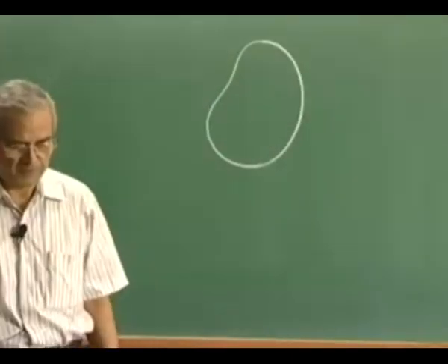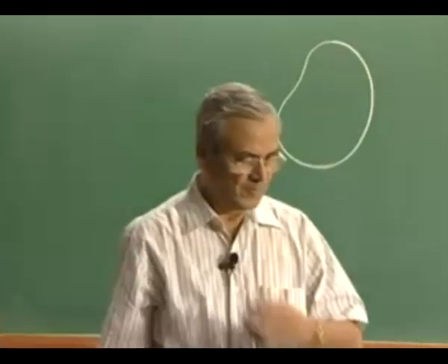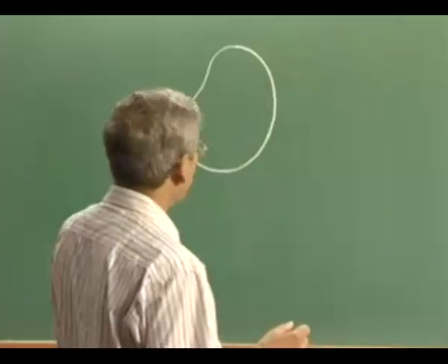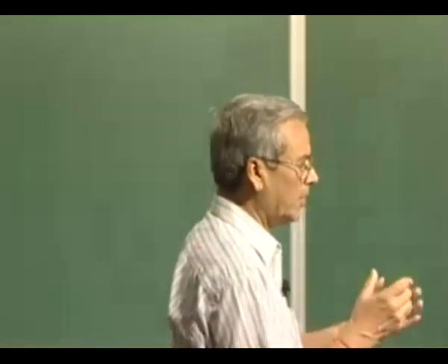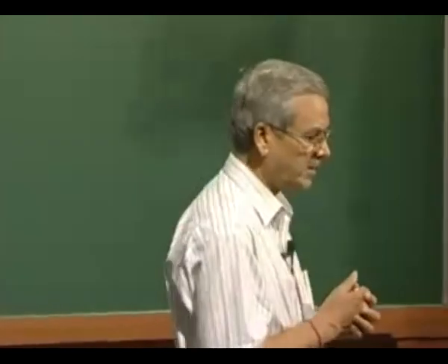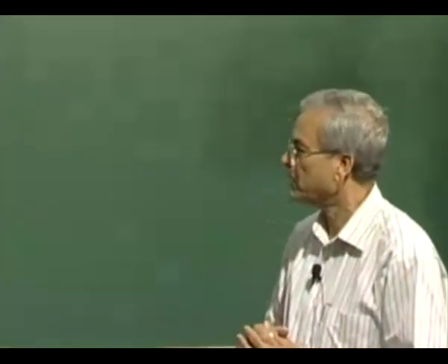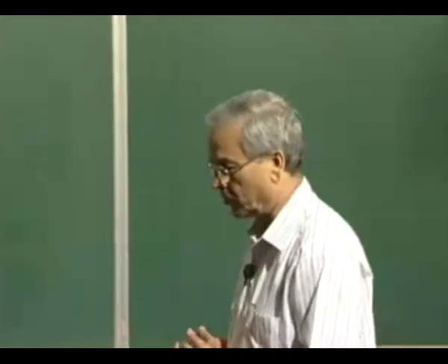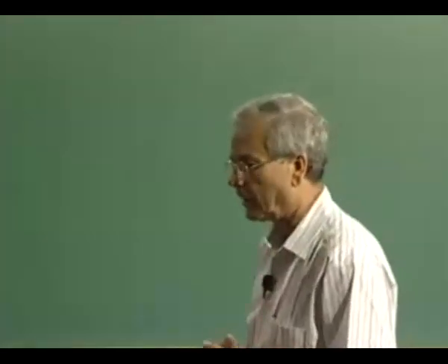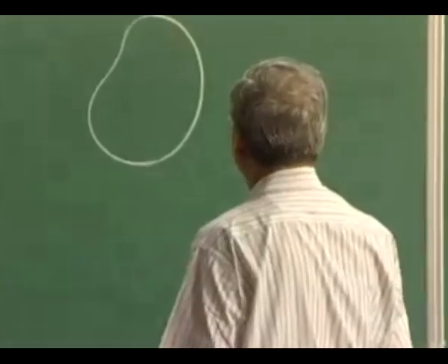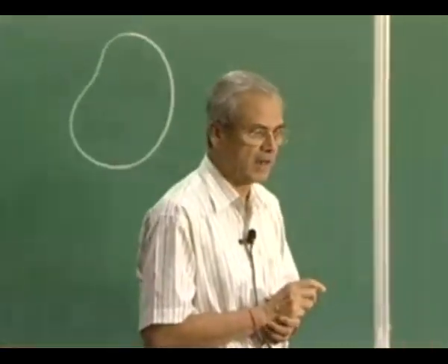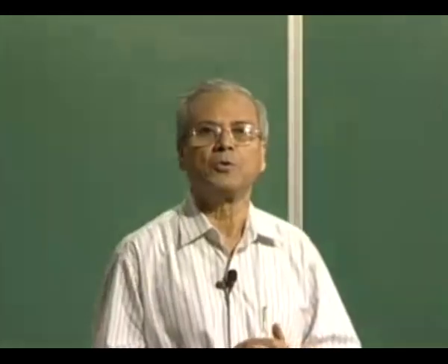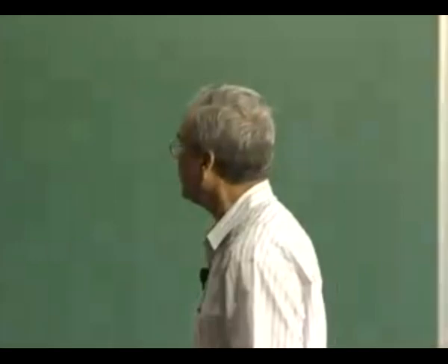So if this be the rigid body under consideration, its translational motion can be considered to be a particle type of motion, where the whole mass of the rigid body may be considered to be concentrated at the center of mass, and the angular motion about the center of mass or any other fixed point O can be represented by an instantaneous angular rotation about an instantaneous axis which changes its position both relative to space and time.